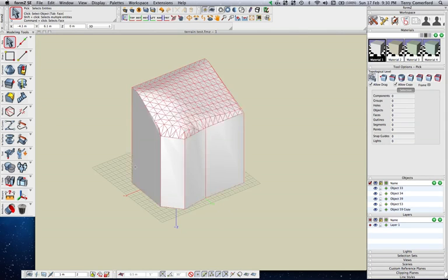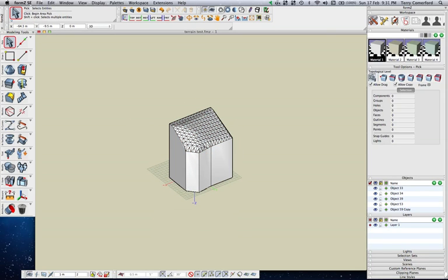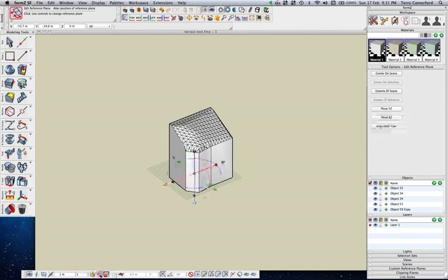What I actually want to do is establish a new reference plane and then lock that one. I'll start with this bottom reference plane down the bottom here, but then I'll come across to this point down the bottom title bar called Edit Reference Plane, and I'll edit that reference plane, which opens up a set of axes that I can move and rotate with.